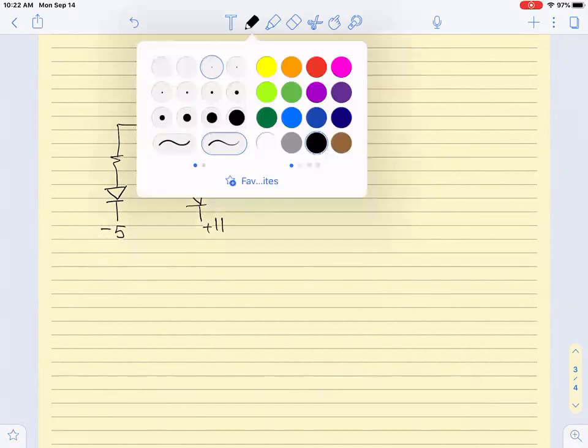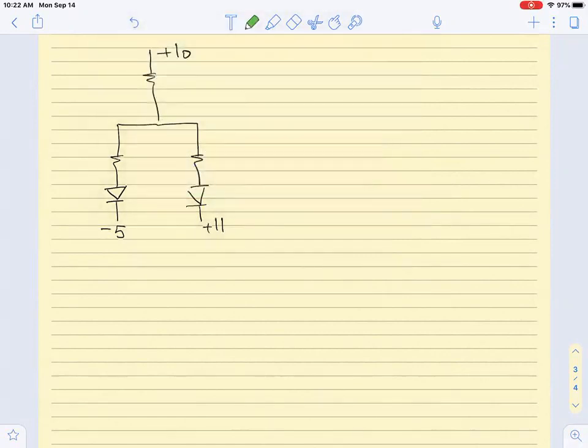Okay, and this is because we expect the current to flow from the positive to the negative, right? So we expect we can have this current, but this one will oppose it, right? Because the voltage from this side, coming from the two sides, is lower than this one, right? So it cannot create a current. Yes, sometimes the values of the resistors, 1, or 2, or 3, may affect the voltage division at the intermediate node, and how much current I have, whether it goes from anode to cathode or vice versa.